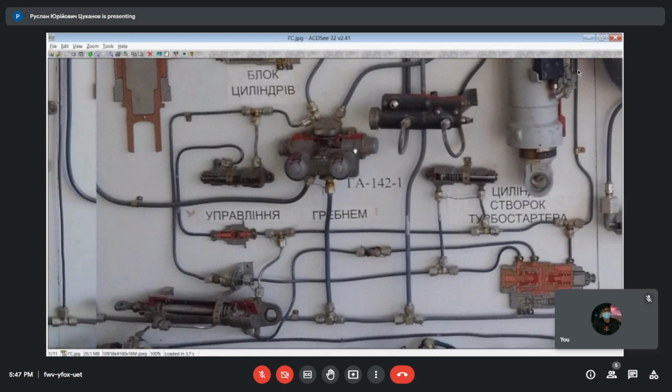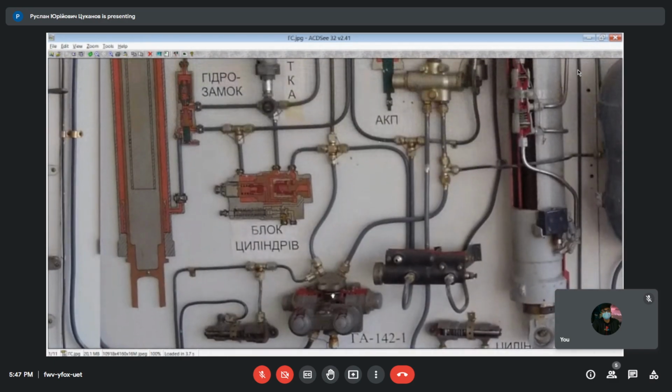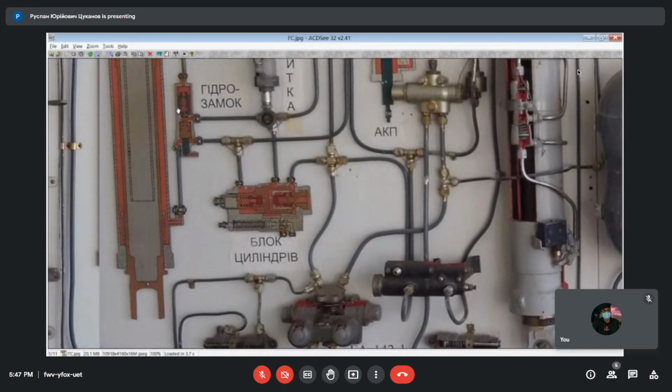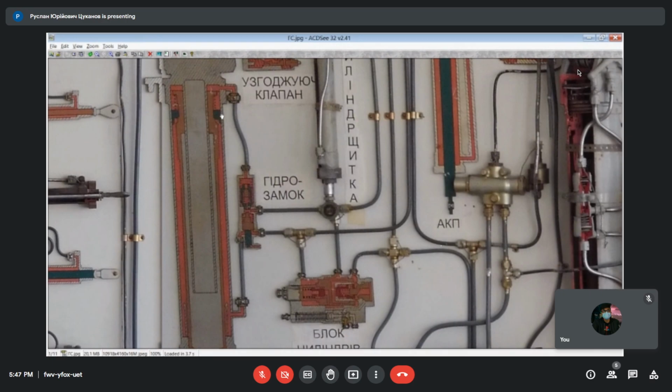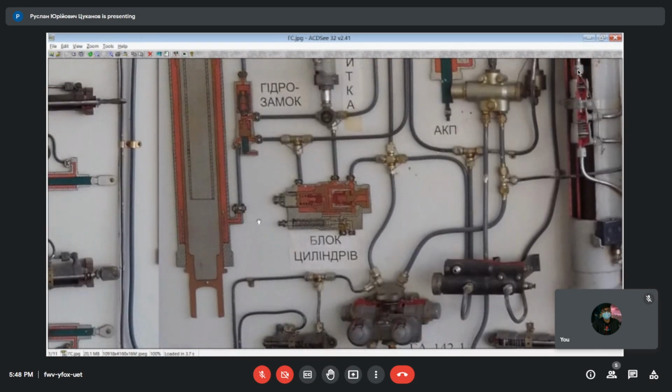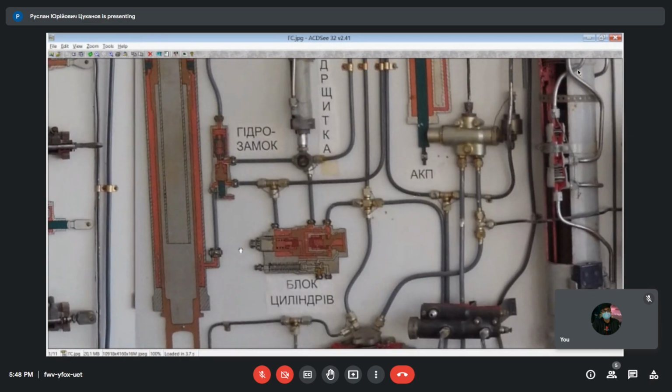Okay, after that, the hydraulic valve will be de-energized. In this state, the hydraulic lock will block the extension cavity, so that even if the mechanical lock built in here, which we will discuss next time, fails, the hydraulic lock prevents landing gear retraction in case of landing and loading application to the landing gear.